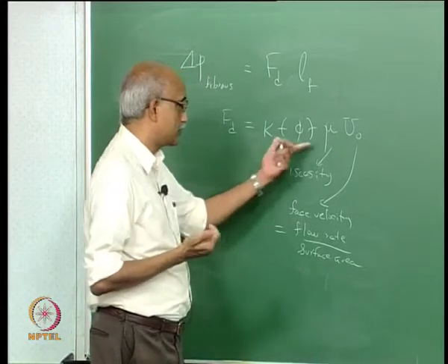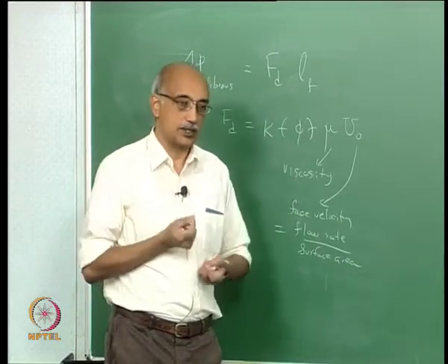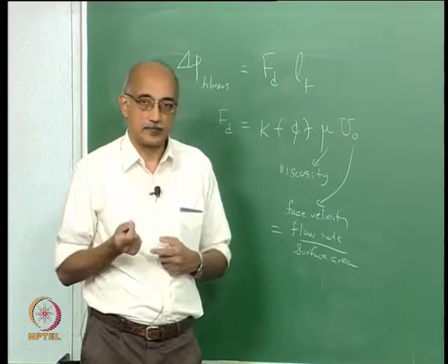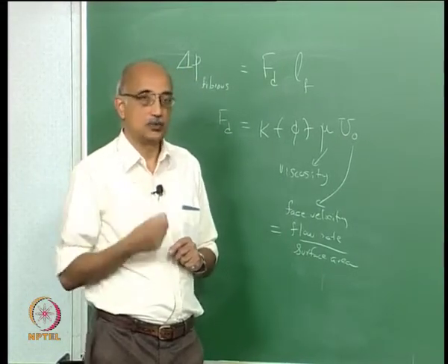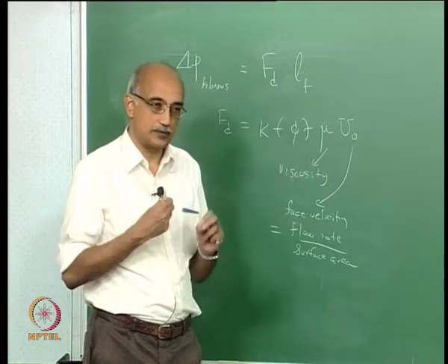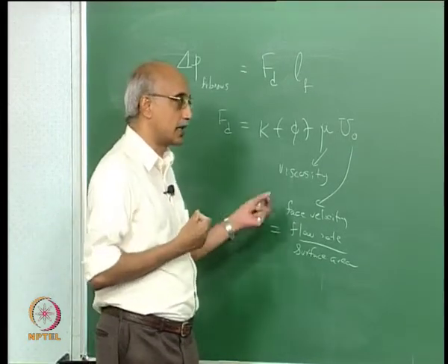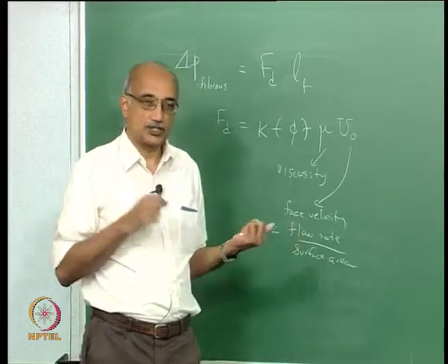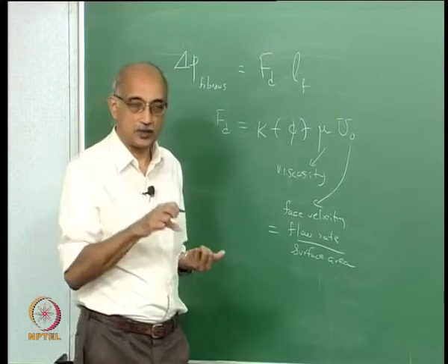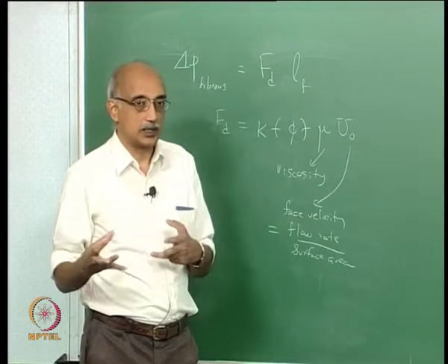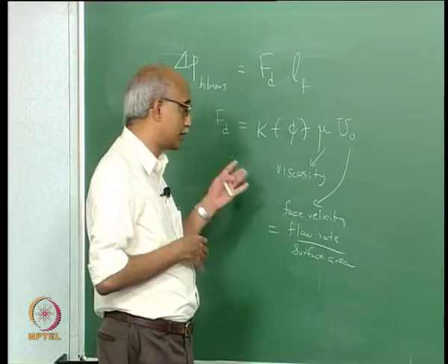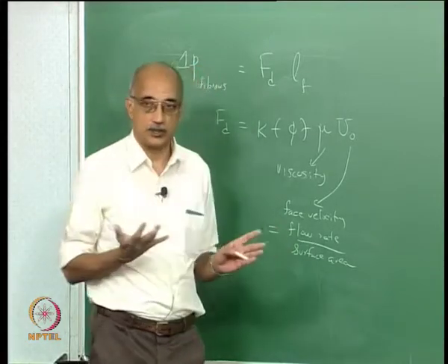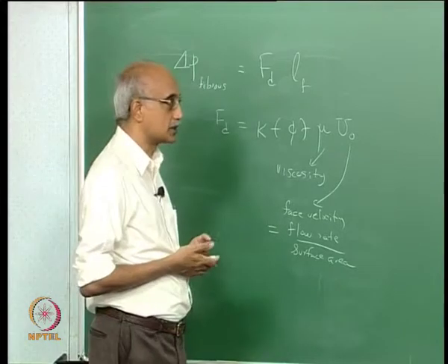And actually you can see from this expression that filtration of liquids is going to be a huge challenge, primarily because of the viscosity. The higher viscosity will lead to higher pressure drop. So the filtration of liquids is a very different challenge, and we will see later that it's not only because of this, but even some of the transport mechanisms that are used to capture particles are very different in the case of liquids. Some of the mechanisms that are present when filtering gases are absent when you're trying to filter liquids, and that presents a challenge as well.